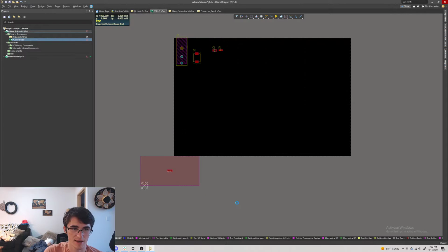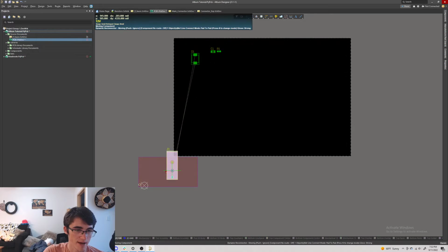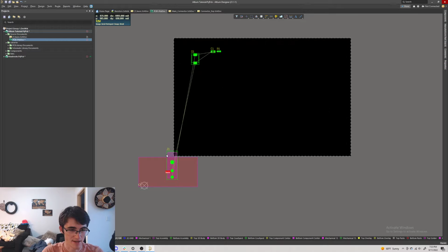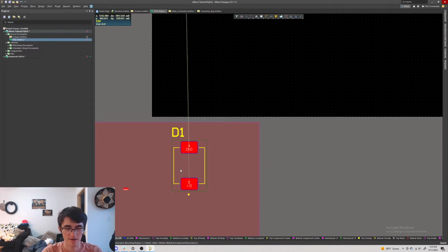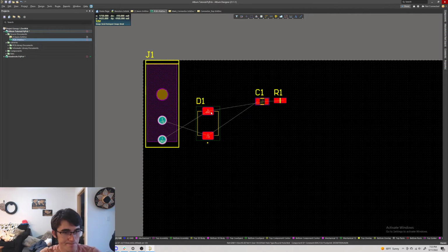You actually can, that's interesting. You'll see here if you move the part back in, and then if you regenerate it, maybe it's because it's outside the whole thing. Yeah, so now you can see the diode isn't highlighted. Another way you can get rid of this is deleting it. You can make it in your settings where it doesn't generate every time. If you want to stay sane, that's probably a good idea. But yeah. So now you can see this change from its name from button to ground.